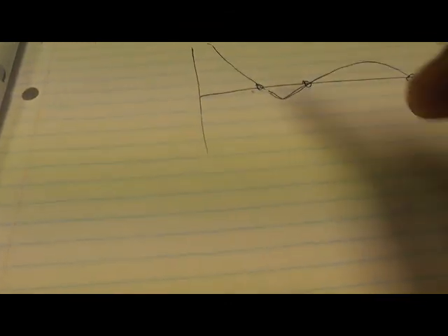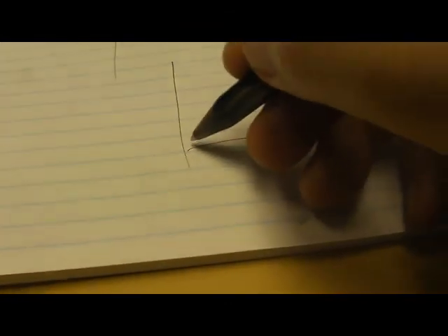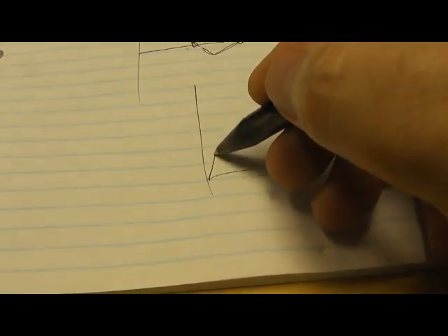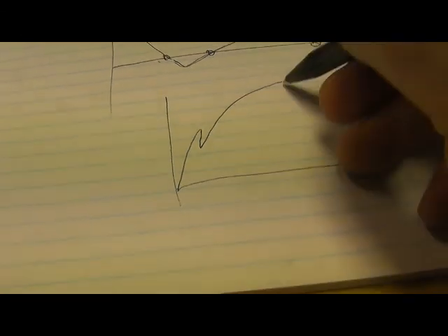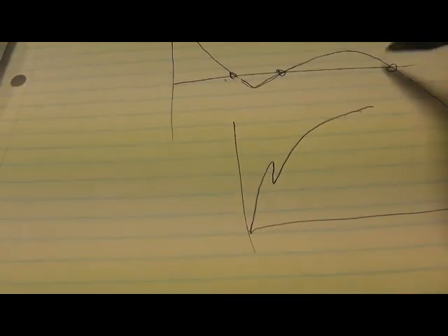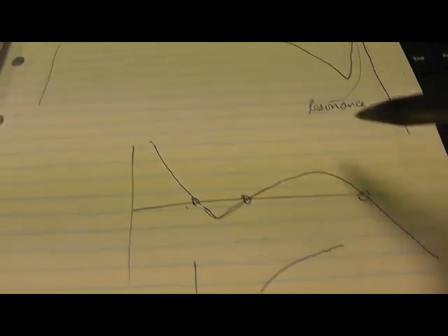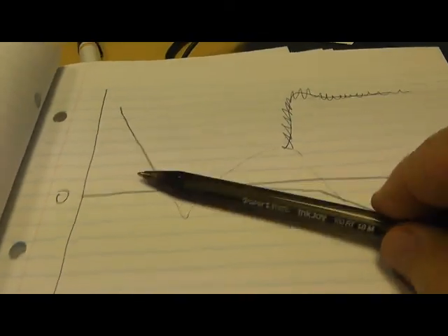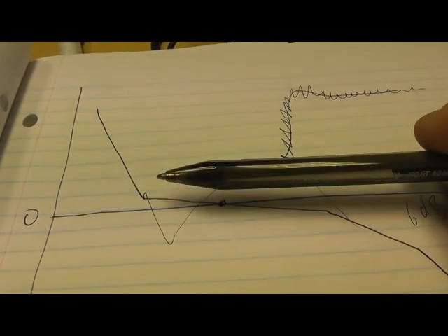And what I've found, and you don't see this in any textbook, is that you get responses like this. It sort of goes up, and then it goes in reverse, and then it goes up again. It does strange effects like that, which you don't really want. So although it's interesting to do that, you want to keep the slope -20 dB per decade nominally, or flat if you want 2 phase advances.